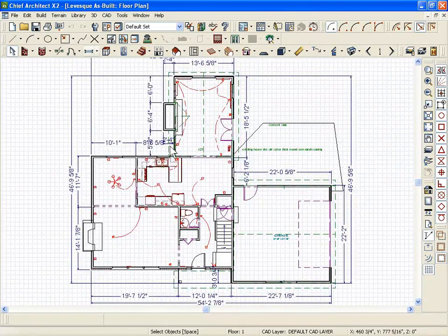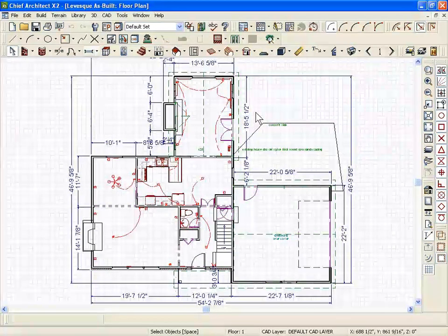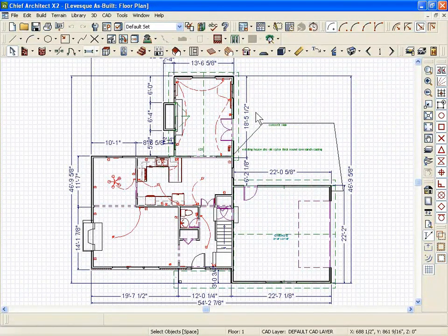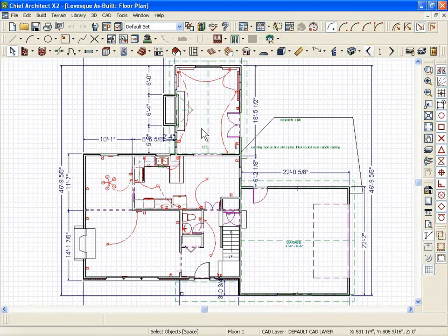When I went out and measured the house, I didn't finish it. I had things still floating around, details that I needed to clean up. In this plan I probably took 150 pictures before I left, too. In fact, that's the first thing I do when I measure a house: take the pictures first, then you have an idea what you're going to be drawing. Don't take the pictures last, because usually you're running late and you won't have time to take all the pictures you need to take. Take the pictures first.